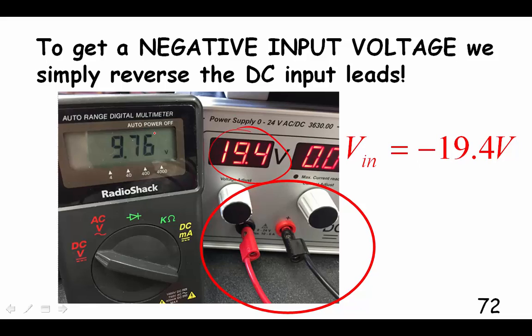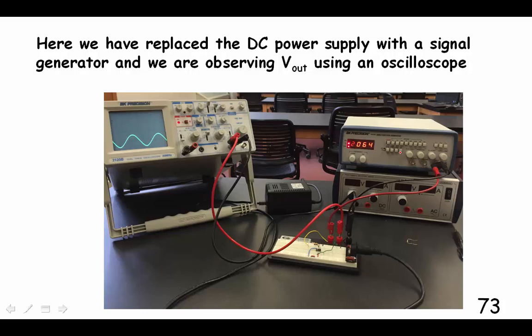I put in a voltage of -19.4. Again, it's negative because these 2 terminals are reversed, and then I take half of that, and I get that, and it's positive because it's inverting the negative sign that I have on the input.